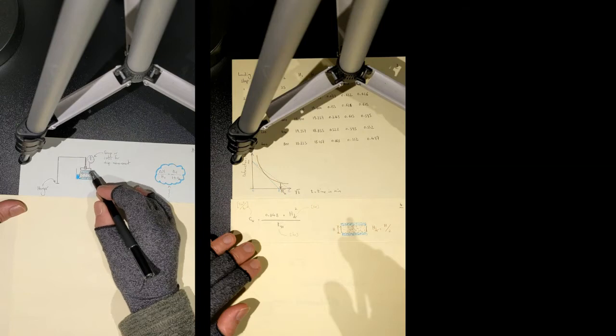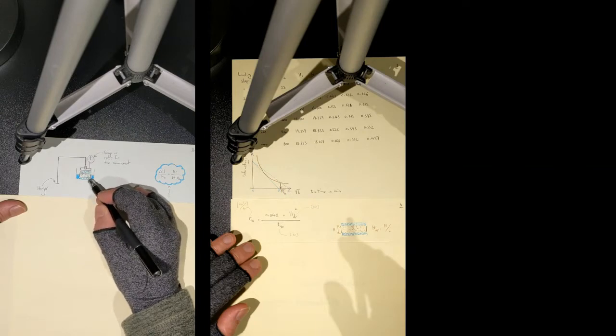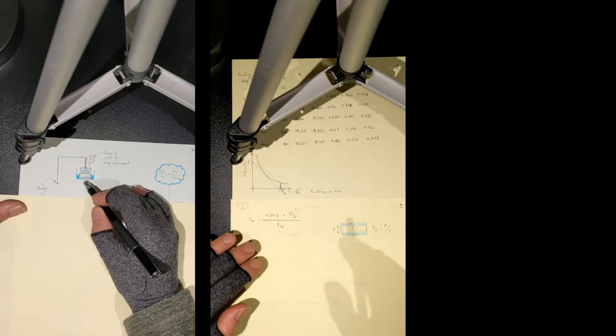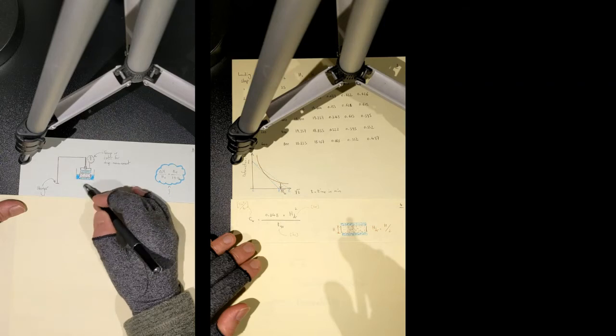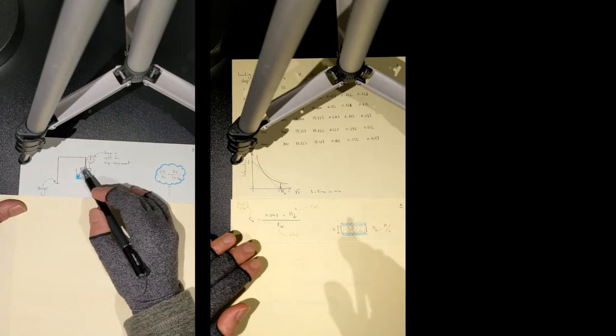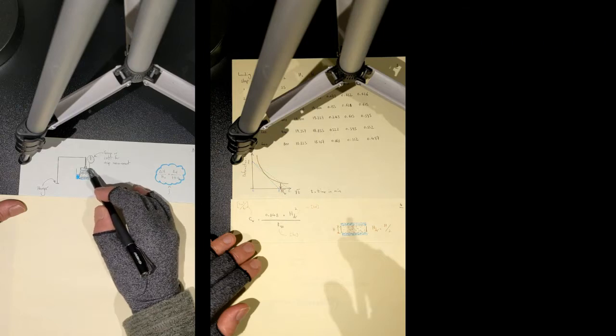The porous disc is a metal disc or a stone disc, which is, as the name suggests, porous, and it conveys air and water. Now from the bottom, your porous disc is sitting in a chamber, the blue chamber, that's your water bath. Your water bath will be filled with water at all times. And from the top, your porous disc underlies a metal cap, which is basically your loading cap.